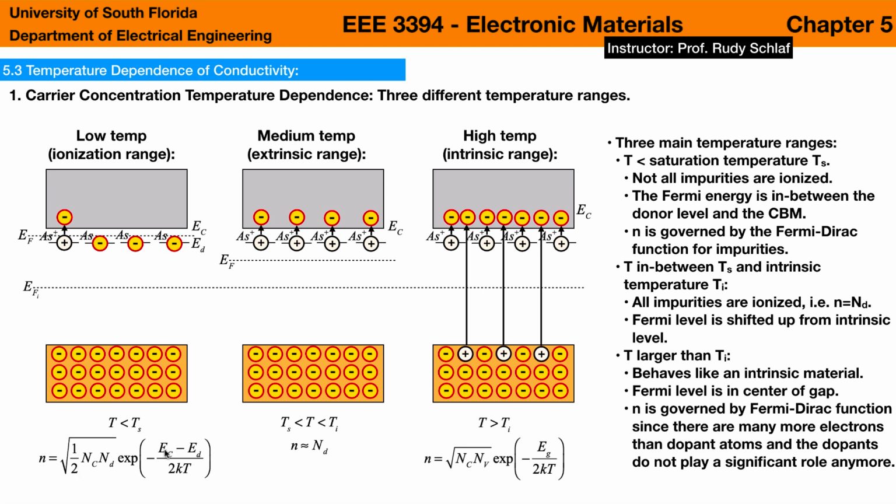Also, the band gap is replaced by the gap between the conduction band minimum and the donor energy level. In a way, this is sort of making its own intrinsic semiconductor here between the ED and EC levels, with ED acting as the valence band, because we have thermal generation across this little gap between ED and EC.